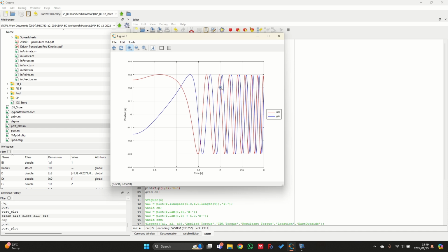Of course, you can go as small as you possibly want to, but if it's not going to contribute to the actual accuracy or the computational performance of your dynamic analysis, then it won't be necessary to further refine your reporting time step. So to strike a good balance between computational efficiency and accuracy is paramount to these types of problems as well.